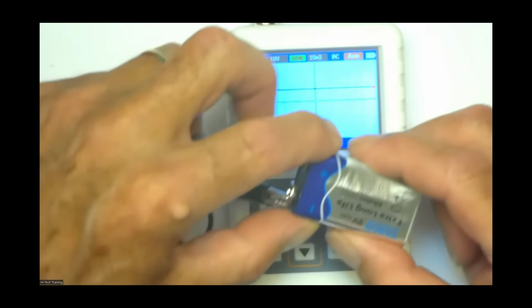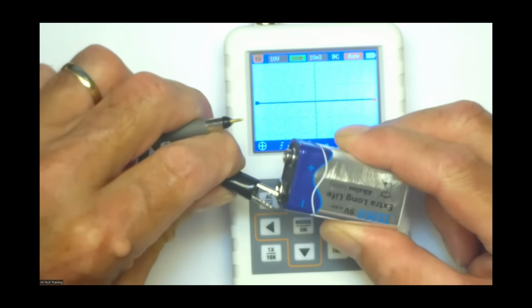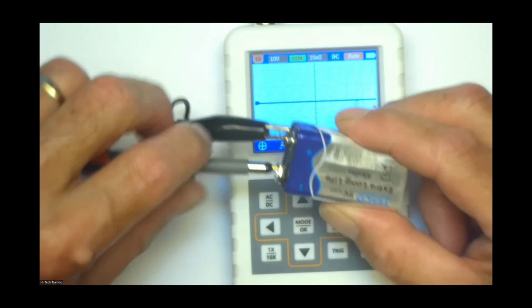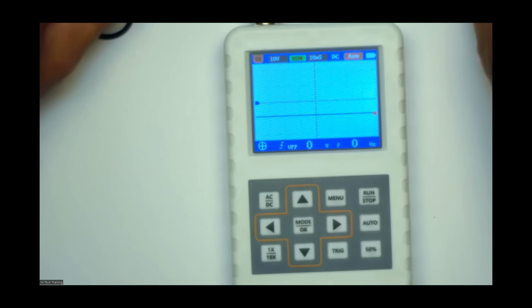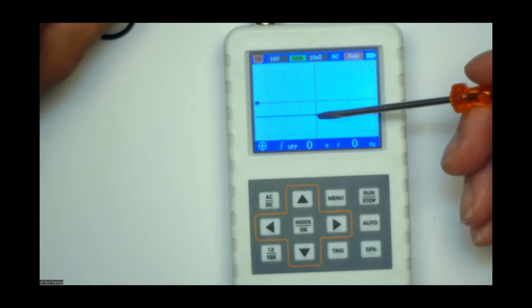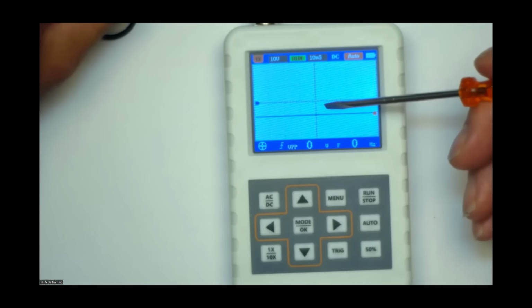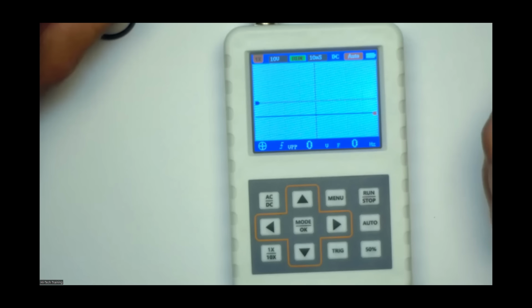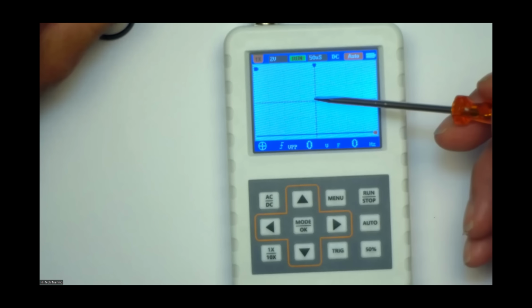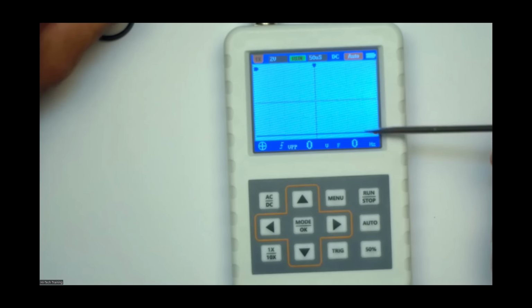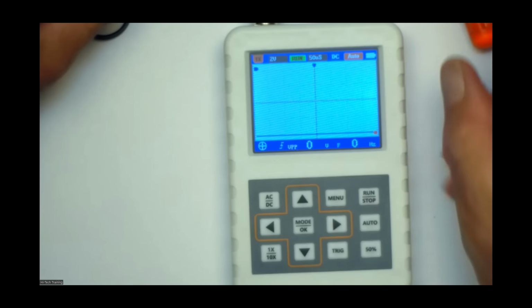If you want, you can get your battery and turn the terminals around on it. Let's go on here, this one, put your positive, put your negative there, positive here, yes, swap around, and you go minus 10, or well, about minus 8 on this one, because our battery is running at around 8 volts. Okay, so that's a nice little scope there. Yes, if you wanted to use that one, you can put an auto set on it as well, and it should automatically set up for itself. So here, when we went to auto set, it has just automatically set up for us, and 0 hertz, because you have 0 hertz with DC voltages.